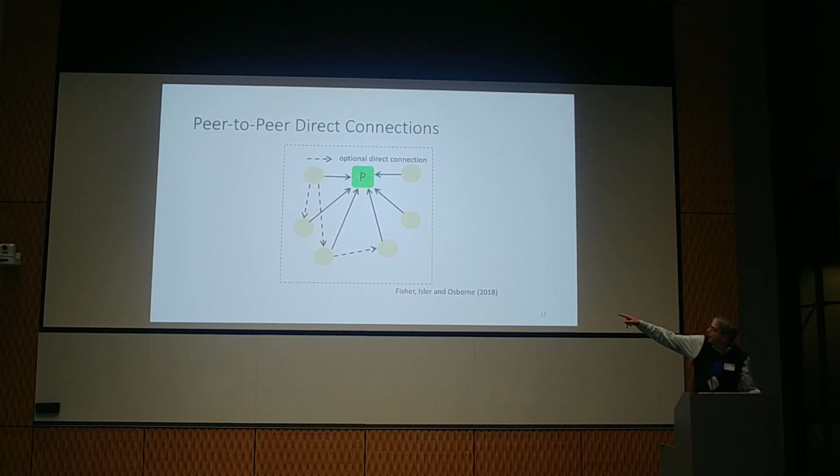So any of these BACnet SC devices, once they've been authenticated to the hub, can then go and make connections to other BACnet SC devices and check their certificates both ways to make sure that they're allowed to talk to each other. So this should improve performance, especially in big systems.